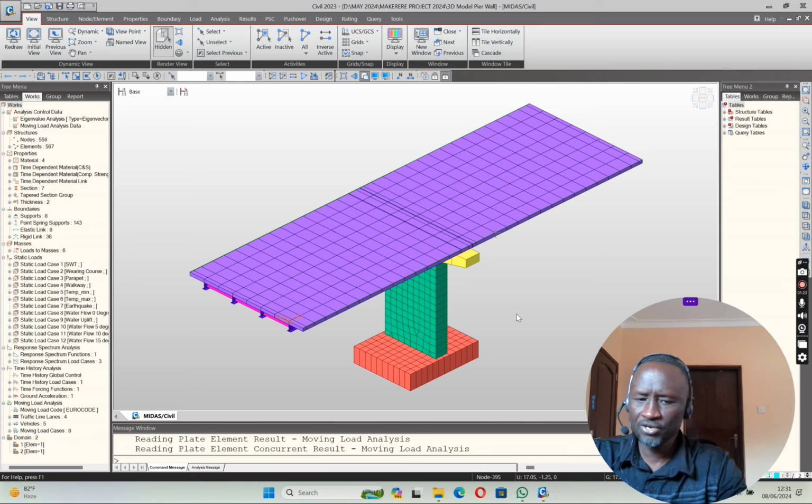And then the scour depth, the scour calculation. You guys who are doing water resources, I think you will also learn how to design for water scouring. That is very, very important. Scour depth normally guides the depth of foundations and also the treatment required around the pier. We have local effect scouring, the local scour, and then the general one, where at the end you combine the two to give you the overall scour depth.